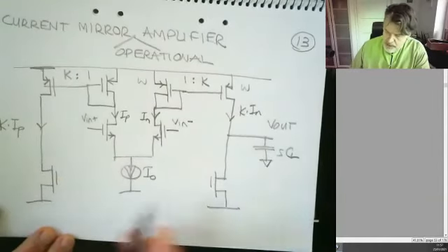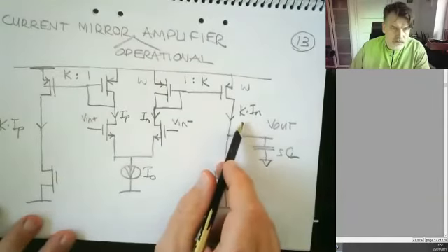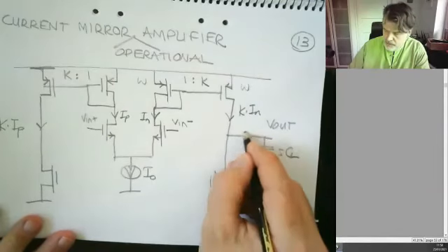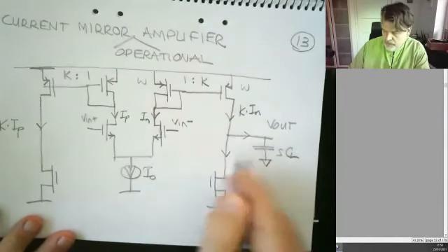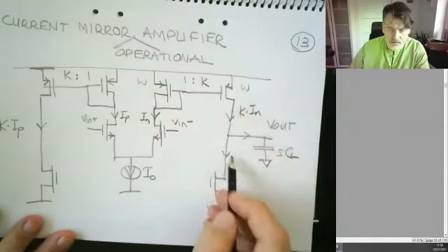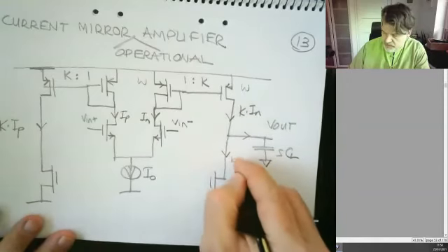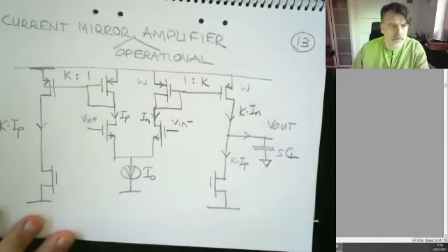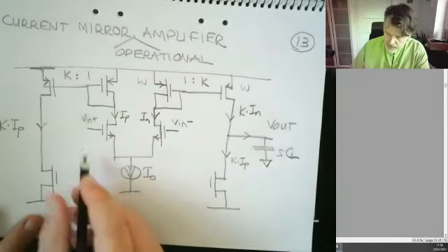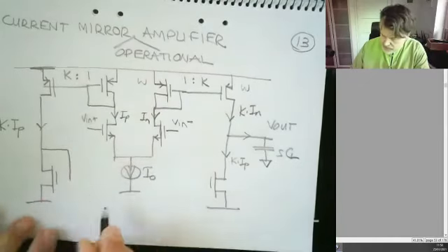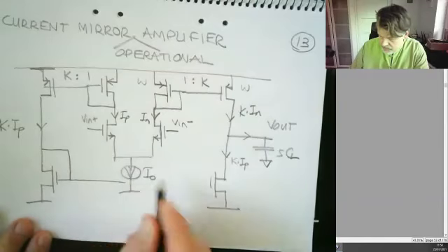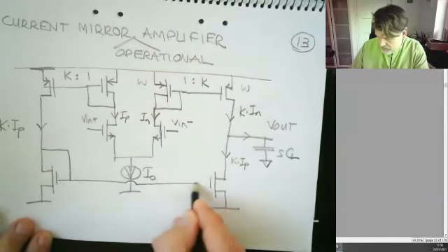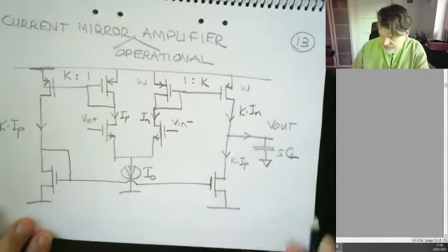All right, and I want to create a difference current. So whatever comes out at I out here, I want to create something which is the difference between current. So this has to be K IP then. And how do I guarantee that? Well, I guarantee that by adding a current mirror also here to the other transistor.